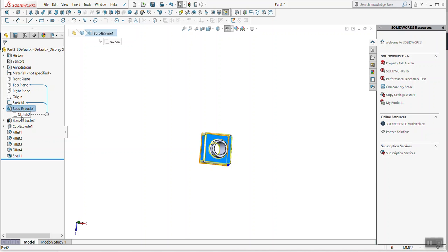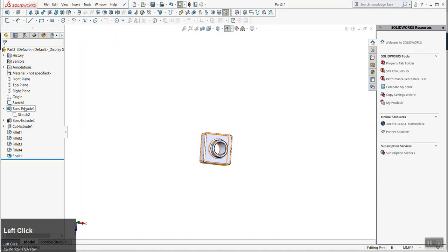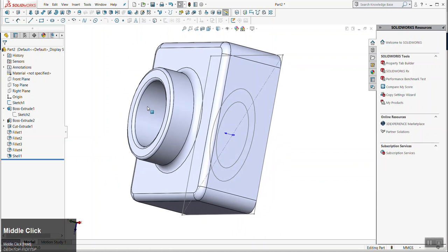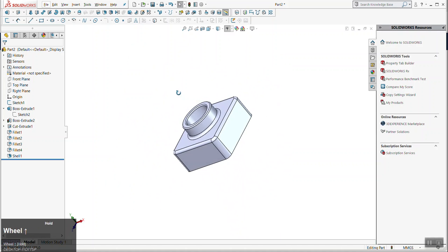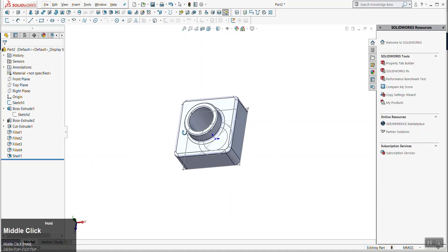You could do that. It's not ideal, but I see what you're saying. So here's a nuance for you guys. I don't know if you've noticed this. It's really small here, but you see how the sketch is blue and how this is gray, or like a thin black frame? This means the sketch. Another thing I keep toggling is Alt-V, which hides and shows a list of things. It defaults to just sketches and planes, I think. That's useful, like if I don't want to see the sketch anymore, just to observe the part, I can do that. If I want to see the sketch, I can view it.